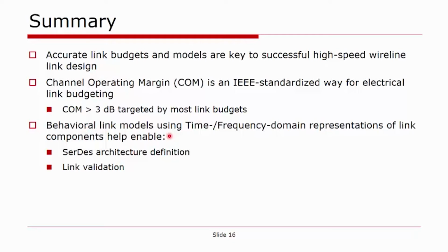And then on the link modeling side, we saw how we can use behavioral models for different components of the link with a mix of time and frequency domain representations to guide SerDes architecture definition and link validation.